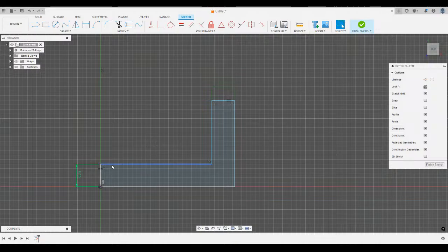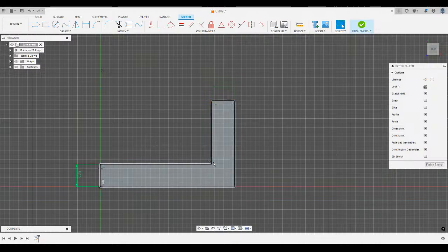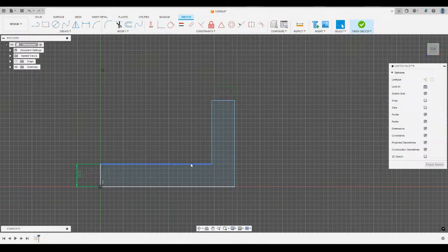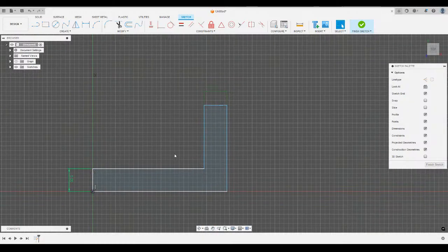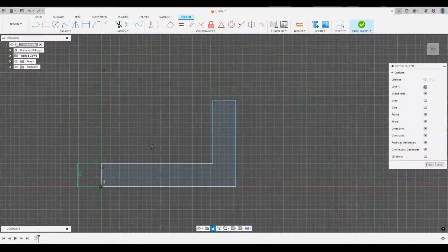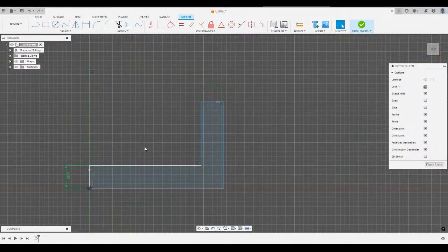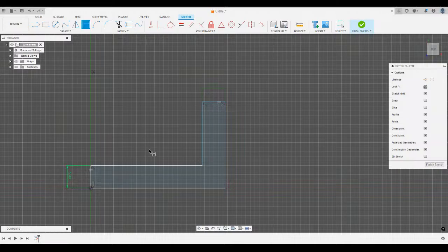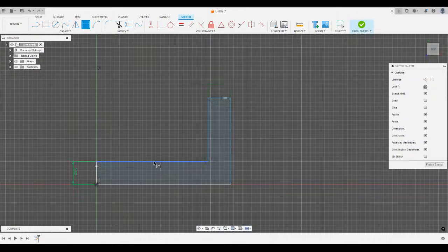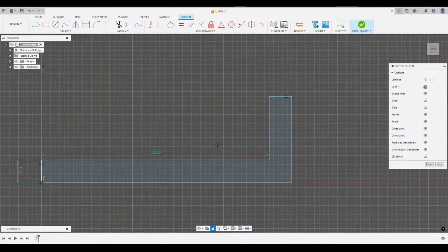And then the length of this line right here is going to be my inner radius of the dish, because this is going to make up half of it when we revolve it around this vertical line here. So what was it, Will? 100 millimeters in diameter? I think it was 100 millimeters in diameter. So you go 50 in the radius, right? Yes. So the inner diameter, if we want it to be 100 millimeters, for this we're going to make this 50 millimeters, half of it, because it's a radius.